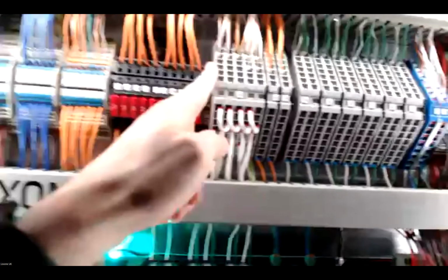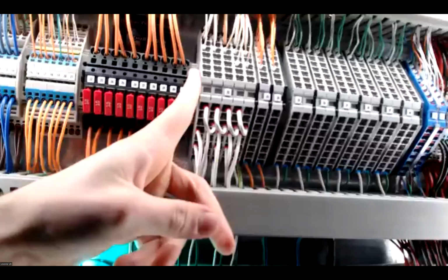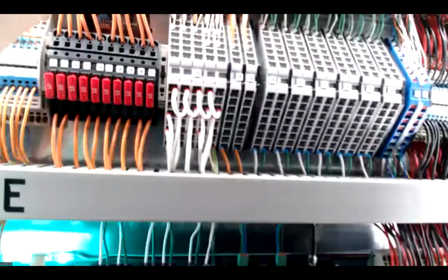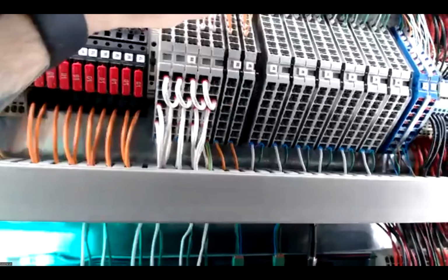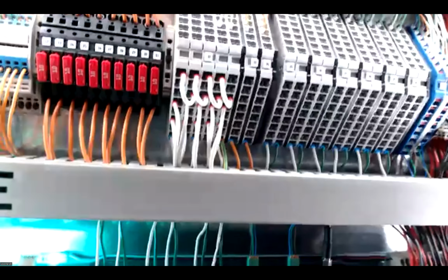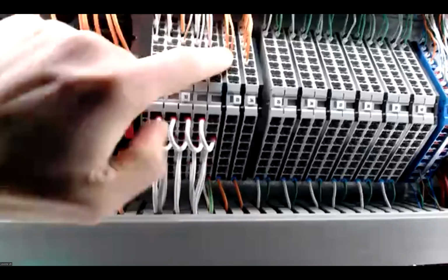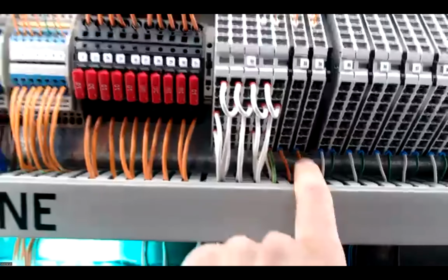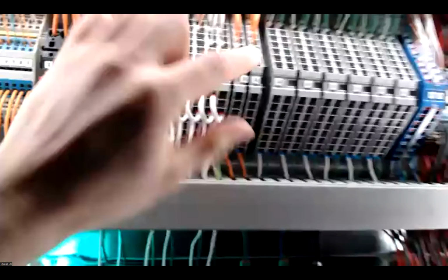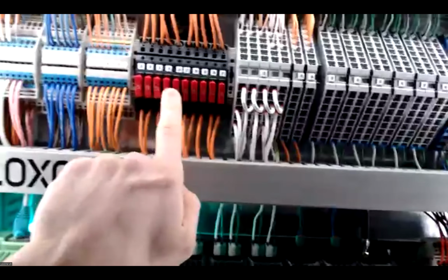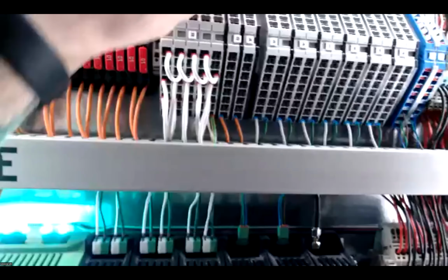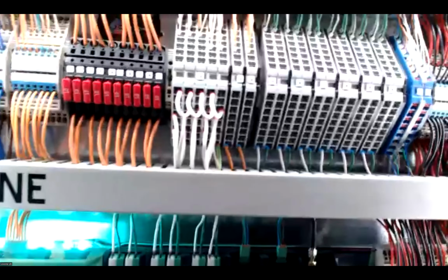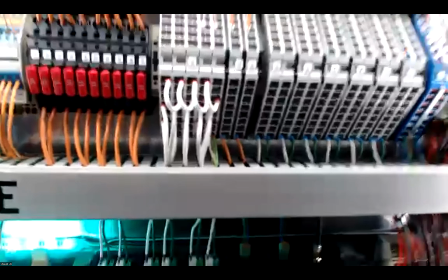I'll say this is a much better use of the terminal blocks, because you can see we have all the 24 volts going out, and this is going to be for the periphery devices. So every single presence sensor, tree, nano 2 relay trees, everything else we have. And we obviously have the power supply coming from the bottom. But maybe what's going to be better in here is to have a smaller power supply or have a blade fuse in place, because if this circuit is fused, we're going to have a little bit more protection for the small devices.